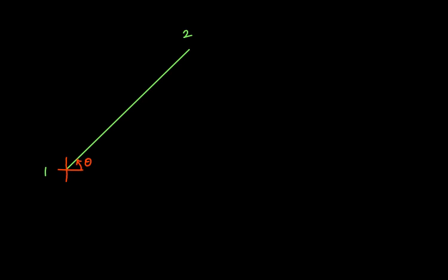Fine. Now this truss member is subjected to certain magnitude of forces, as a result of which nodal point 1 is getting displaced. You see, a truss is a bar basically. So in what direction is nodal point 1 getting displaced? Well, it can get displaced only along the length of this member, because a truss is a collection of bars. All right, so the displacement is q1, and the displacement of nodal point 2 is going to be q2.